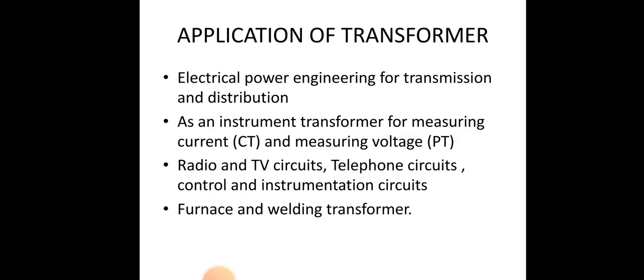So based on construction, it is classified into two types, that is core type and shell type. Based on voltage output value, it is classified into three types, that means step down, step up and auto. Based on the input supply, it is again classified into two types, that is single phase transformer and three phase transformer. So next one, application of transformer.